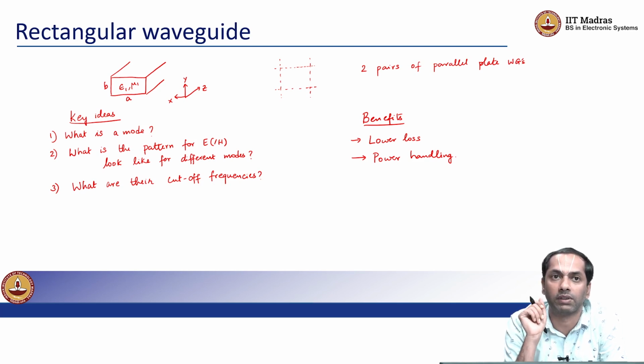So, in the case of rectangular waveguides, we can actually handle very high powers, right, which is why we see these very often either at the transmit side of your 5G and 4G base stations, and also in satellites, right. When the satellite is transmitting some information to the ground station, the transmit side of the satellite would actually use rectangular waveguides in order to transport power or handle the electromagnetic fields. In fact, you can also play with the material that's within the rectangular waveguide, right. By pressurizing it with air, you can actually improve the power handling even further.